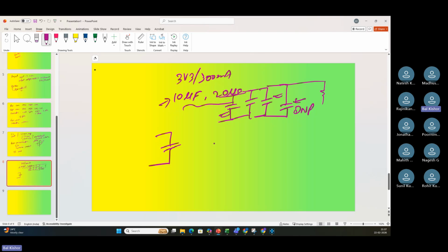The second answer is, yesterday I was explaining about the data sheet. There you would have seen there was an increase in the current. Okay, a sudden increase. That time there was a dip in the voltage and it was reaching like this. So this is I, which is changing from, let's say, 1 milliampere to 200 milliampere. So a sudden increase will make your voltage output go transient low. This will also be mitigated by using a higher value of capacitors. That is one thing. But the value calculation we will see in switching regulators. Here I don't have the answer.